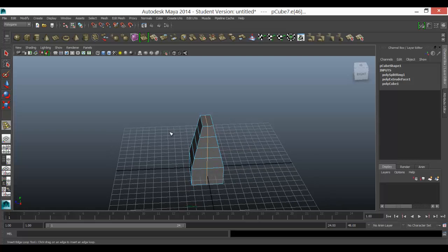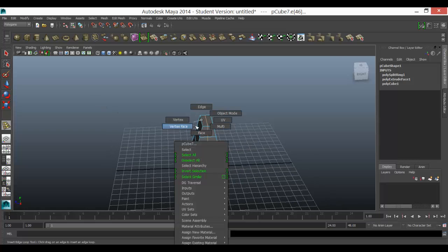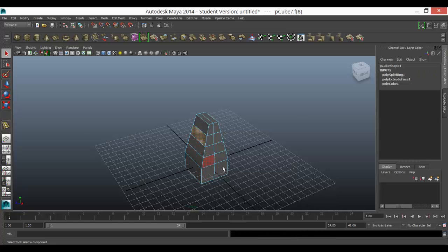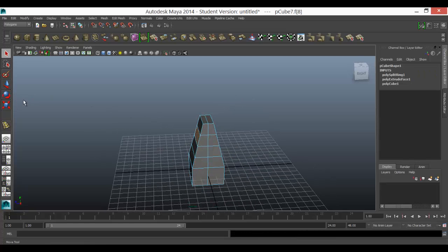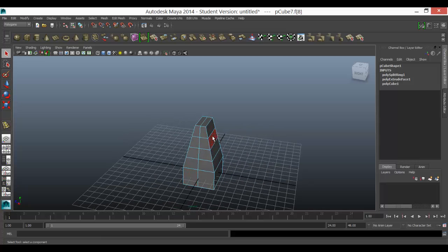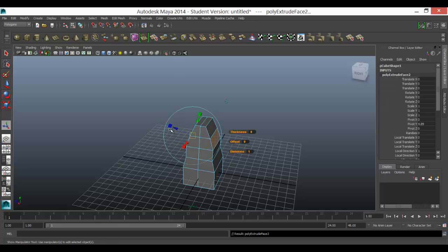Okay, so how to extrude. I've done one extrusion. Let's go to this face on the side. There we go, face here, and I'm just going to extrude that. Now if I wanted to, I could select 2 faces, shift select the other face as well, and I could extrude that out sideways or pull it out sideways, and then extrude it sideways, and you can see it automatically knows what I want to do is on the opposite side as well.